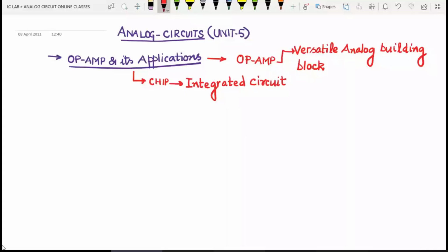Yes, sir. So the chip is also called an integrated circuit or an IC. And I told you why we call this an analog chip: because by altering the external components, we can change its functions. That is why we call it an analog IC. We can make it function as a rectifier, that is, a device for conversion of alternating current into pulsating direct current. Here we make use of a rectifier called a precision rectifier, and we build a circuit using this.